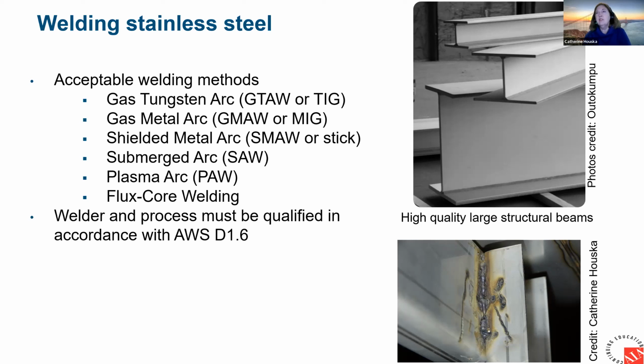I was underneath these beams in a seismic zone, and every weld I saw would have failed based on, well, numerous issues. So I kept praying that there would not be a seismic event while I was underneath them. The lower image: nobody checked the welder qualifications, and they were not qualified to weld stainless steel.